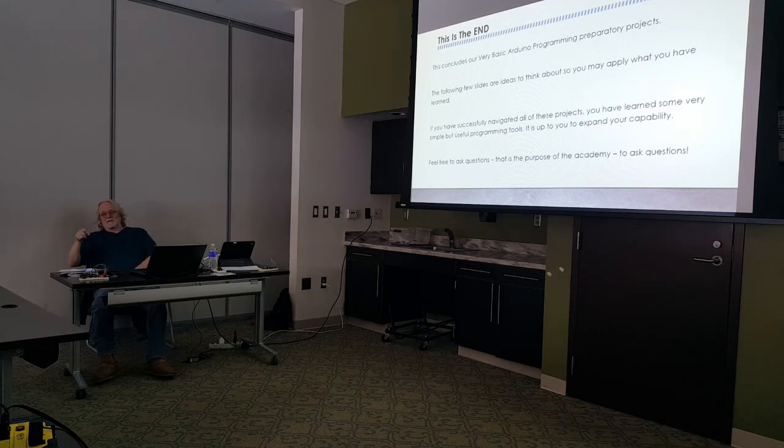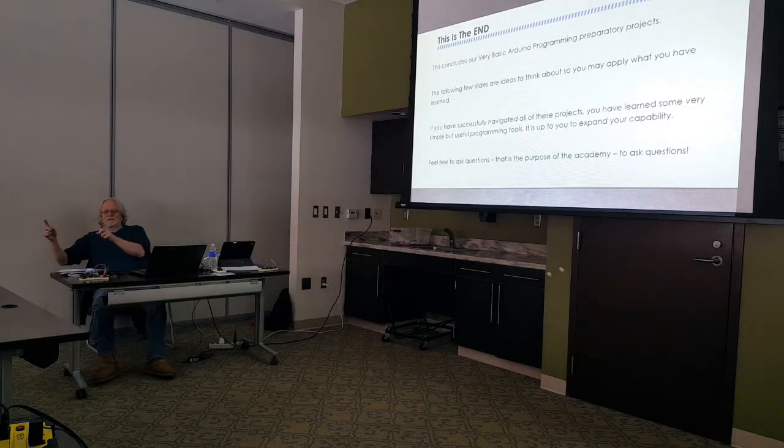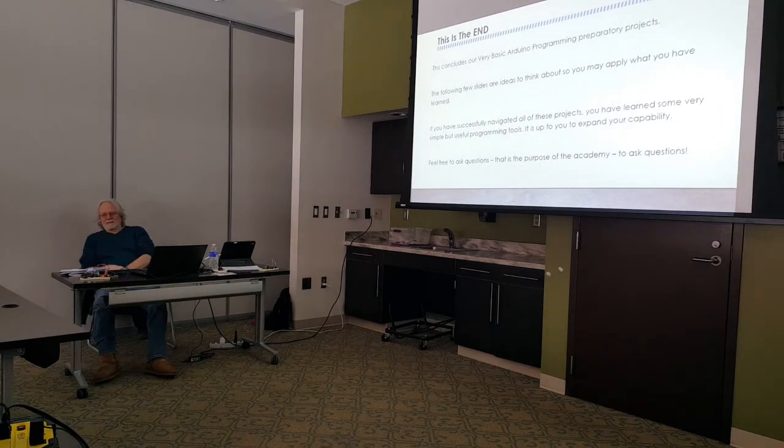And then on the other zero crossing, you read again. The input capture, you could do it, I guess you need an interrupt in there somewhere, but you get the point. I can read it here, and here, and here, so I know the time for the half cycle, so I know the period, and I can calculate frequency. You're not going to do 1 gigahertz. You might be able to do 1 megahertz. You could do a packet modem. Audio would be easy.